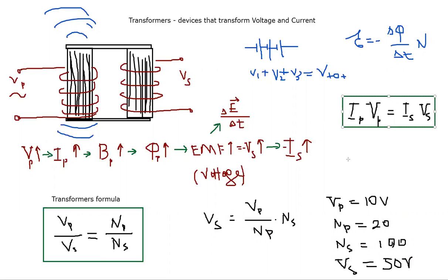However, in some cases, people ignore the fact that they have to force cool transformers so they don't overheat and melt down, and they may not include that energy expenditure in the efficiency formula. So you usually get less energy on the secondary coil.